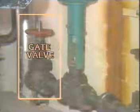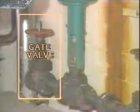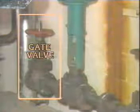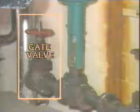Now, while globe valves are the most common type of valve, there are a number of other valve types used in industry. Gate valves such as this are widely used for on-off service. The throttling characteristics of these valves are generally very poor, and use in a throttling application can cause rapid valve wear. As a result, gate valves are rarely used to modulate flow. However, a few designs have been adapted to provide good throttling service.